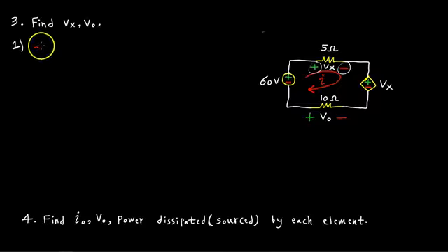Let's see, negative 60. I'm starting here again, going up there with the current flow with that direction that the problem indicated, and I'm going to say plus Vx. Let's go ahead and write plus Vx. Again, let's keep it in the variable form so that we don't mess any directions or signs up. Then we're going to see another Vx, that's going to be a plus Vx there. Then we're going to see a minus V0. So minus V0, that's all equal to 0.